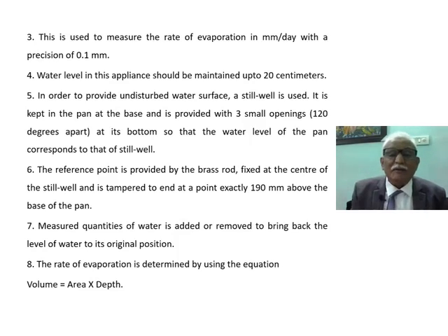It is provided with small openings at 120 degrees at the bottom, so that the water level in the pan corresponds to the still well. This is very important. In the still well, there is a water level. In the tank, there is a water level. So the water level in the still well and the water level in the tank are the same.